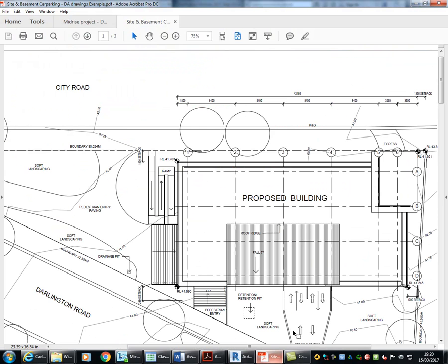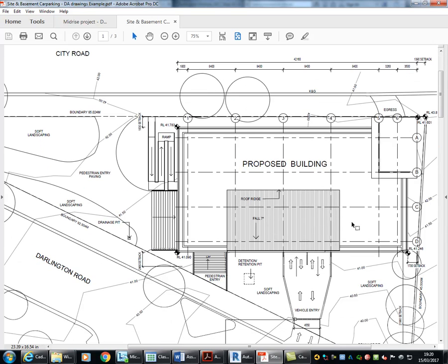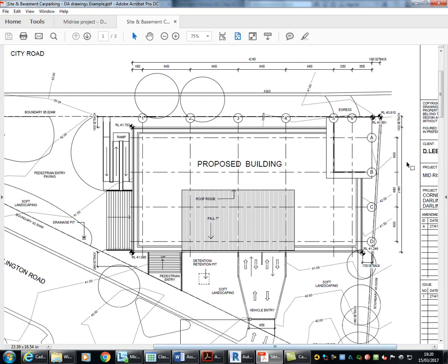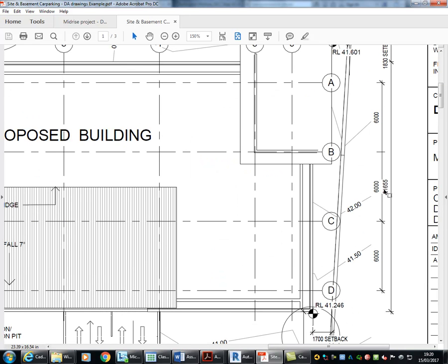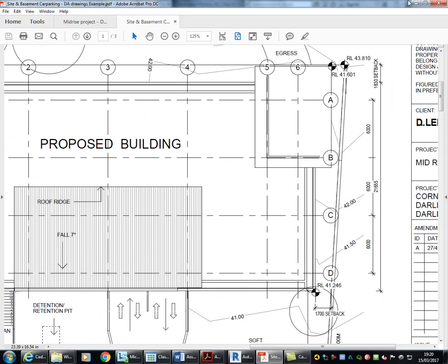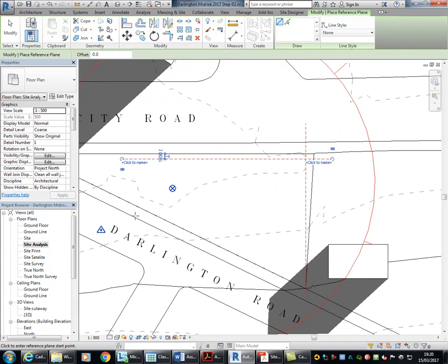And then the next one is, I'll zoom in, 21655. So always when you're working with these things, just make sure the measurement is coming from the object you think it is. So there, it's quite clear it's coming from the reference plane, so that's okay.